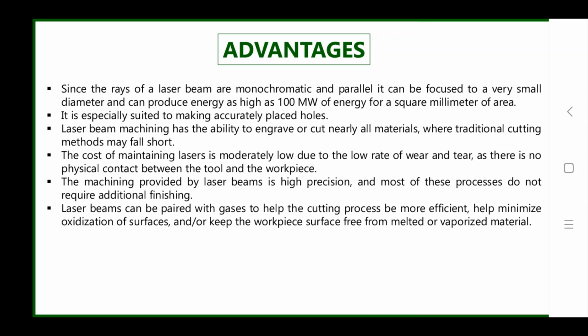Again, laser beam machining has the ability to engrave or cut nearly all materials where traditional cutting methods may fall short. The cost of maintaining lasers is relatively low due to the low rate of wear and tear. The machining provided by the laser beam is highly precise, and most of these processes do not require additional finishing.